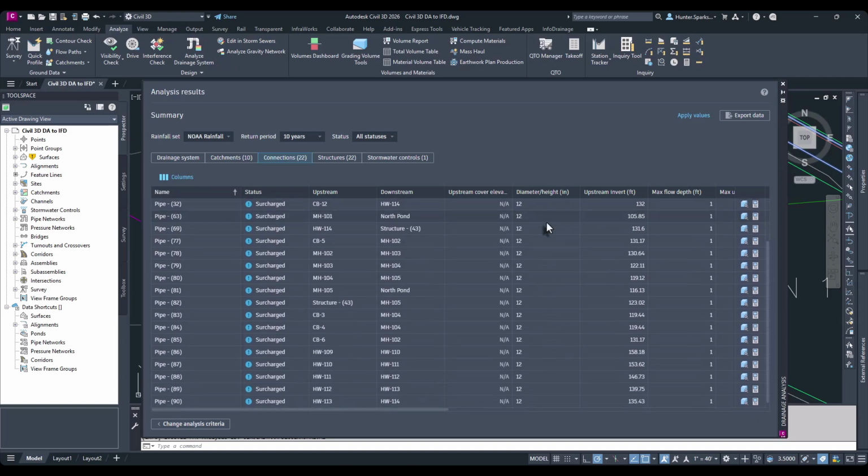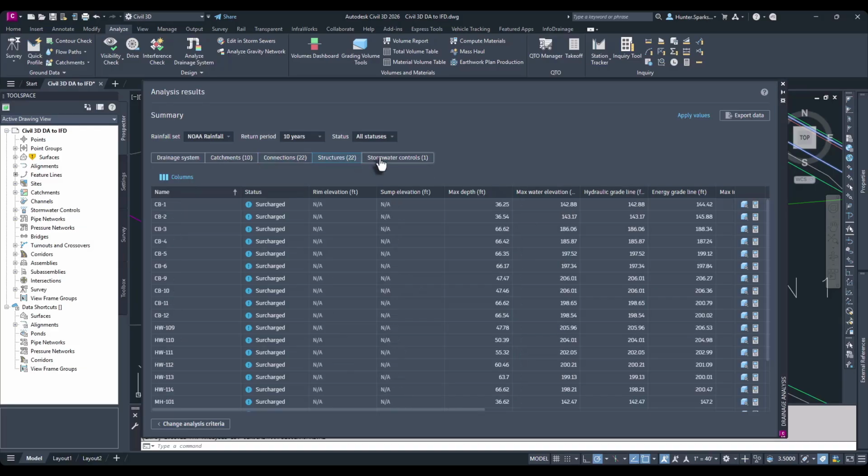And they are all 12-inch diameter. So this is where it shows that this tool is more of a straight analysis tool, testing the system that you have and not a pipe sizing calculator. It doesn't give you recommendations for your slopes, for your heights. So if I want to make changes to these to try and get out of the surcharged event, I can go ahead, manually swap parts, and then rerun my analysis, which is what we're going to do in the next step.